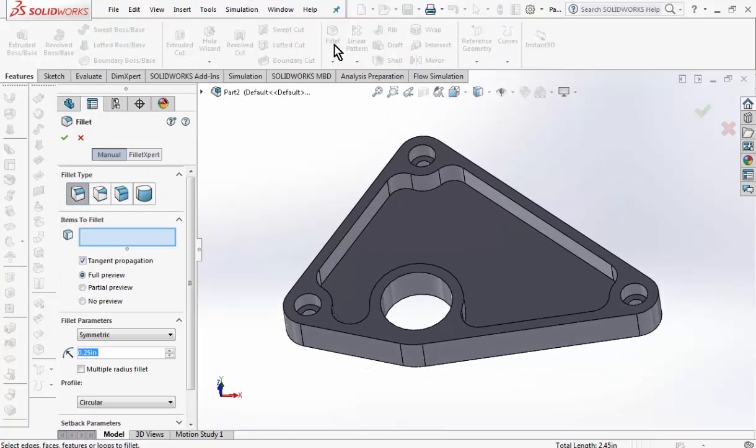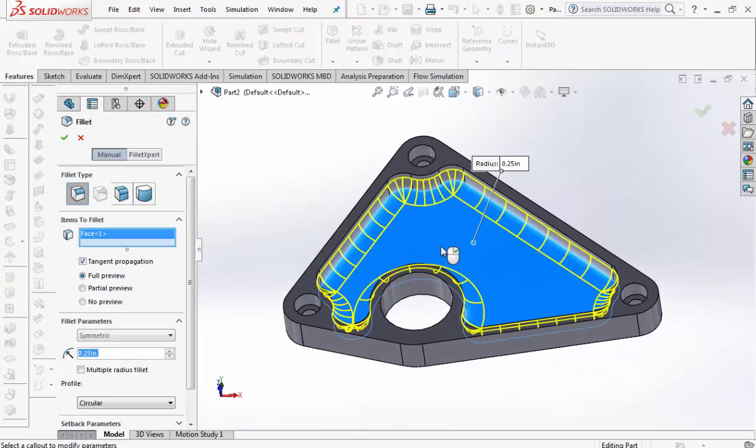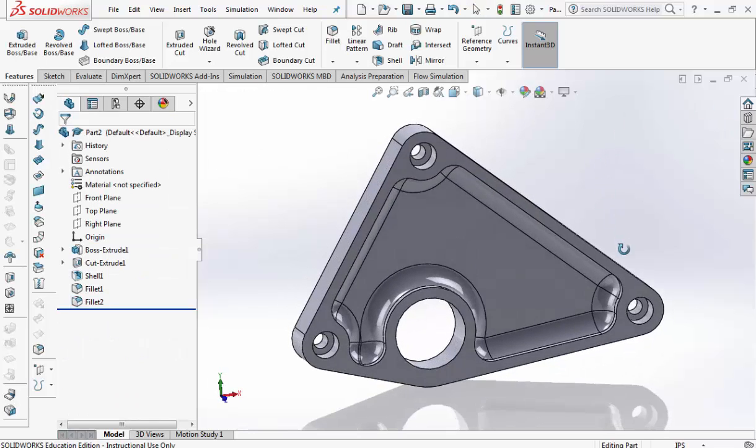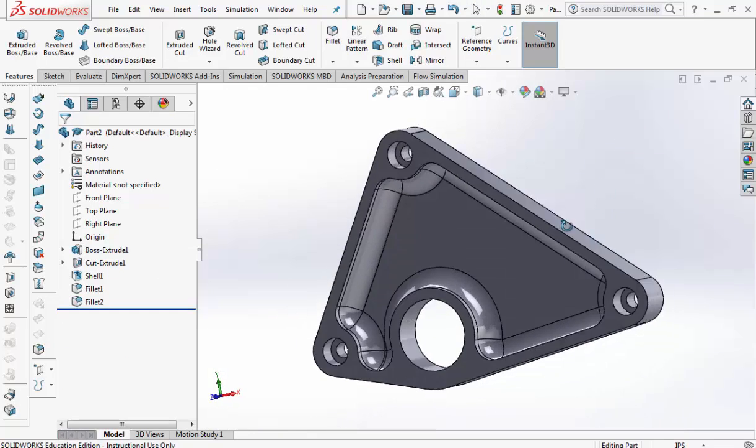Do another fillet, and I don't think you can do it all in one shot. It's got to be 2 separate pieces. Click on the bottom, anything that touches the bottom, the whole perimeter, the whole way around. 0.25 typical. Hit the green check mark. And there you go. Lab 6 Advanced.